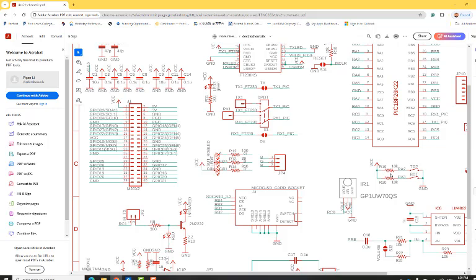The reason is my finger has high resistance. So if I remove the skin and expose my blood vessels and have less resistance, I'll probably still be fine because the power is still low, but it's higher risk. You got it? I'm touching 2000 volts, but never getting 200 milliamps flowing through my body at all. You know 200 milliamps is going to kill a cow. Probably it's only going to take like 50 milliamps to kill me. I don't know.